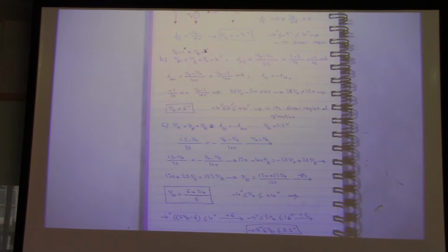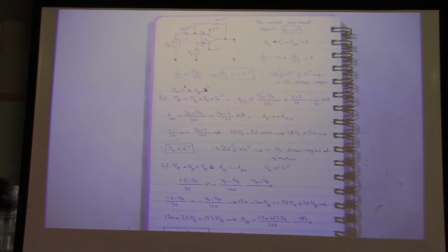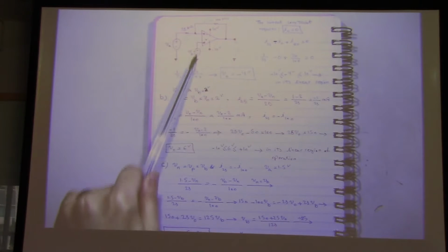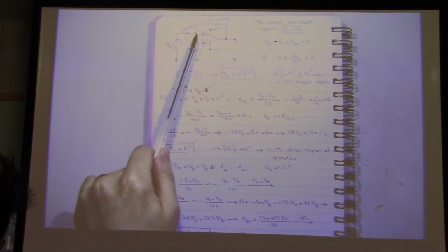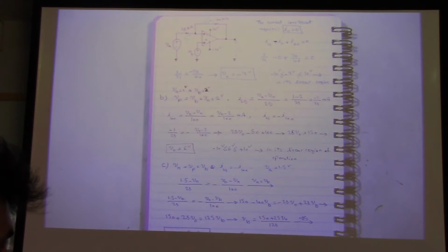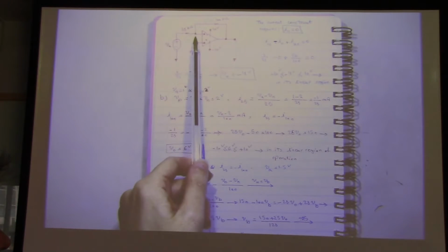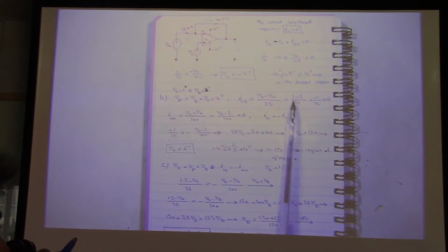Now, VA is 1 volt and VB is 2 volts. So again, VP is equal to VB. What is VP over here? VB, and VB is 2 volts. It means VN, this node, is 2 volts. So how much is I25? Again, VA minus VN over 25 kilo ohm. Now here VN is 2. We have negative 1 over 25 milliamp.